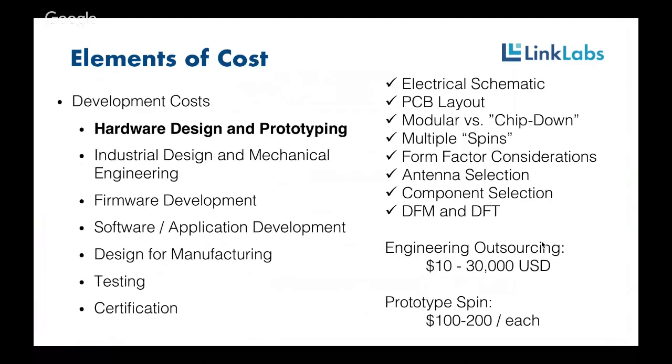So which chip and components are connected to what on your circuit board, and that actually has a big driver into cost, because if you pick really expensive high dollar parts, or parts that are very difficult to put on PCBs, that maybe have a BGA ball grid array that have to be placed with very fine pitch, that can drive up the cost of your product significantly right at the get-go.